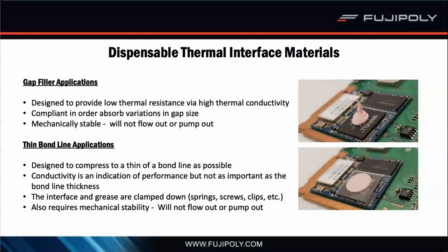Of course, reliability is just as important as performance, so mechanical stability is critical. You want to avoid any pump out or flow out of the material from the interface. Most suppliers will typically have some kind of durability data under heat and humidity for these types of materials.